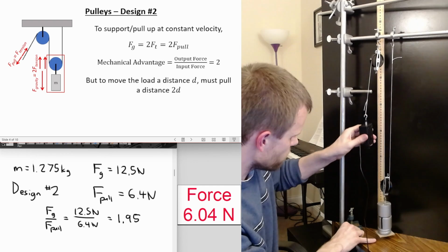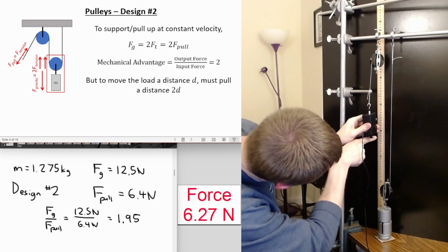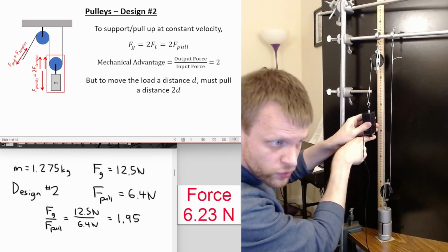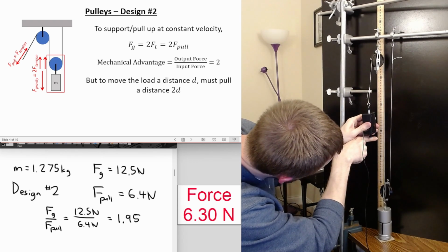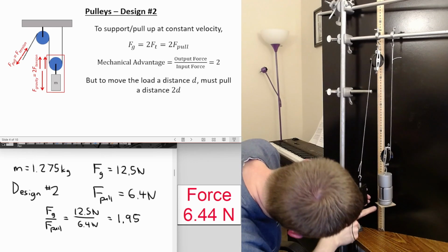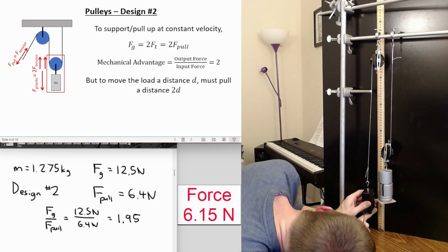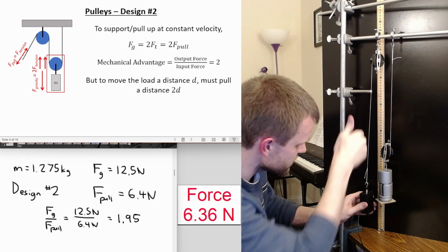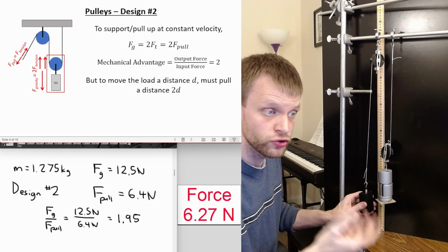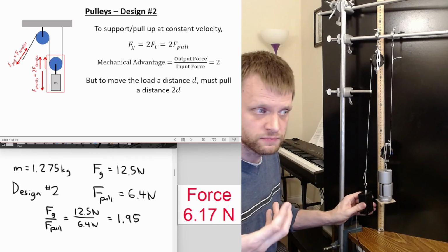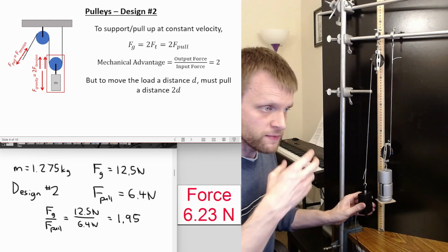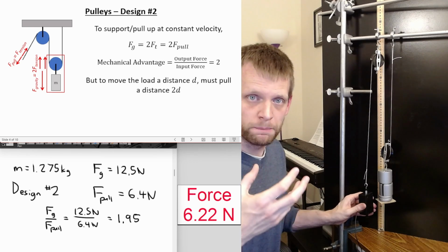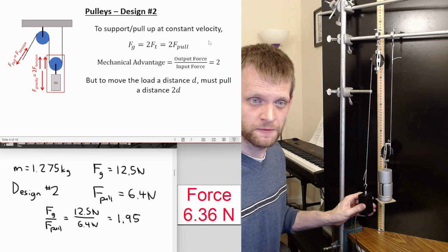So from where I started, on here, this is around 39 centimeters for where the bottom screw on this is kind of pointing. So that has moved up exactly 15 centimeters. Now this is at 9 centimeters. I have moved this thing down from 39 to 9. So I've moved this thing 30 centimeters, and this object has only gone up 15 centimeters. So I'm able to use less force to move this object, but I have to apply that force over a larger distance.